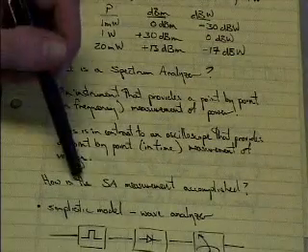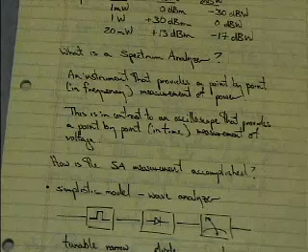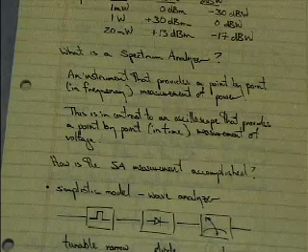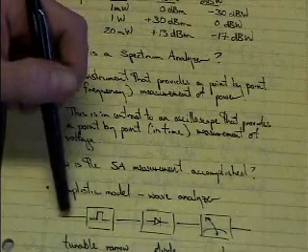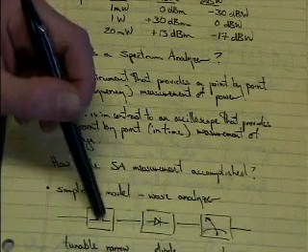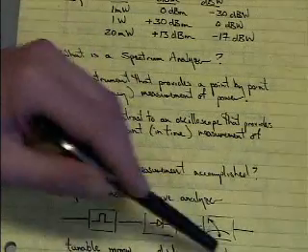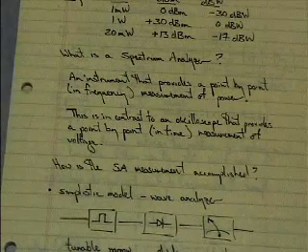Well, how is the spectrum analyzer measurement accomplished? The simple model is that we have a very narrow filter that we tune around the frequency that we're interested in. Everything else is rejected, and so only that frequency passes through, and then we go into a power detector, a diode detector with a meter. So that's kind of the model.